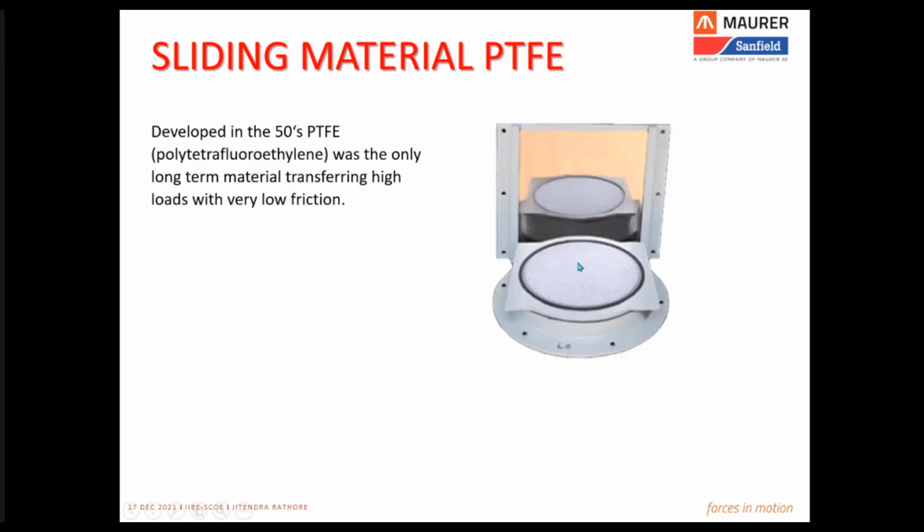Over a period of time, this sliding material gives away, and its thickness is continuously lost. After a certain magnitude of movement, the material might have completely given up. Therefore, the sliding friction of this interface has to be minimum, so that we can achieve longevity, or a longer service life and sliding path, from the two interfaces.